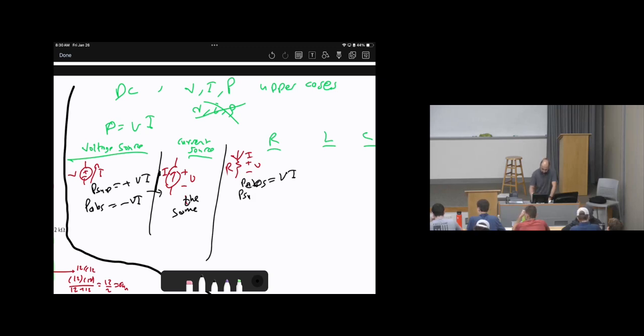While the supplying equals negative V times I. So let me talk about the absorbing more. Equals V times I, right? So positive. Now we are all agreeing that the resistor every time is absorbing power. There is no way for the resistor to be supplying. So every time, maybe you can take it as a rule, when you calculate the power for the resistor, you can take the magnitudes without worrying about the signs and just make it, if you're calculating the absorbing, positive. If you're calculating the supplying, negative.